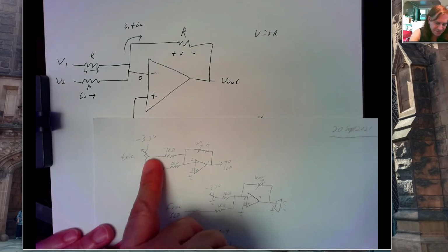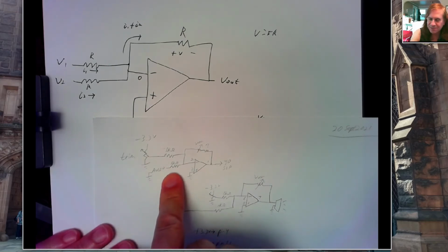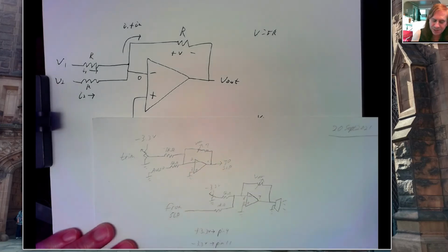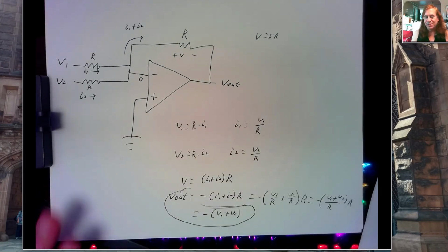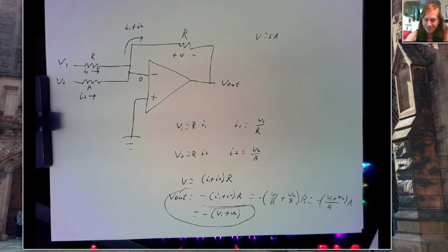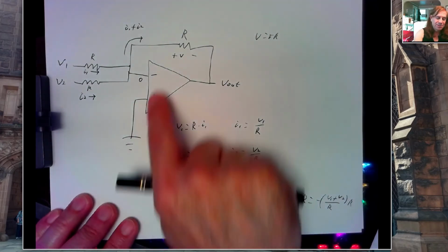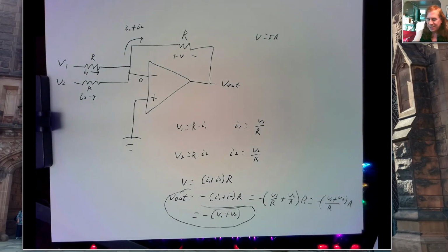So that's the other part of this, right? This is how I can take in a fixed bias voltage and a voltage coming in from a source. We'll add those together, and then we'll amplify it by whatever amount we tune this potentiometer to, and that gives us our output. So really simple and actually really fun analysis of op-amp circuits. And again, it's just 2 rules. No current flowing in or out of either terminal, and no voltage difference between the 2 terminals. And any op-amp circuit that you set up, if it's an integrator, differentiator, summing, differencing, etc., same behavior. And they're pretty painless to work with on a proto board.